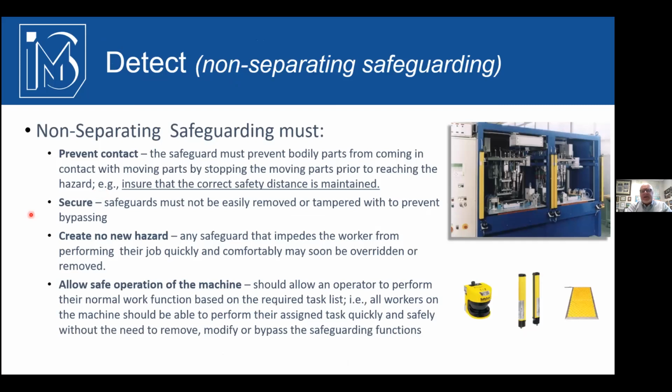So the detecting process, these used to be talked about as safeguarding or non-separating safeguards. That is basically the term you may have heard, and a lot of people still use those. Non-separating is kind of self-explanatory. I don't have any physical barrier to the hazards in here. I'm just going to simply detect it. So there's nothing keeping me from jumping through there other than the detection by the light curtain. So those used to be called